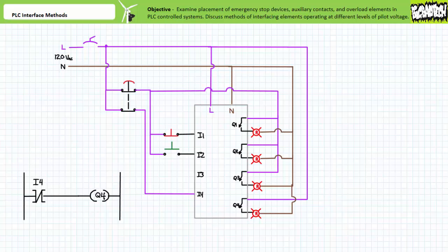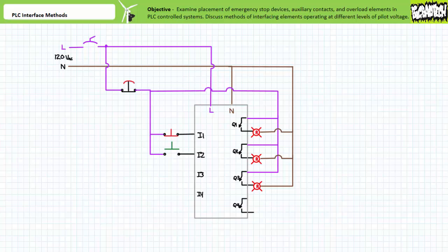It should be stated that the placement of the e-stop is system and application specific and must take into account the needs of the process and those conditions that operators must be protected against. In summary, a properly placed e-stop should disable a system as quickly and reliably as possible with minimal, if any, reliance upon the PLC. In the interest of keeping things simple, let's just assume for this and the remaining applications that the e-stop is a hardwired bottleneck that disables all incoming and outgoing communications to and from the PLC.